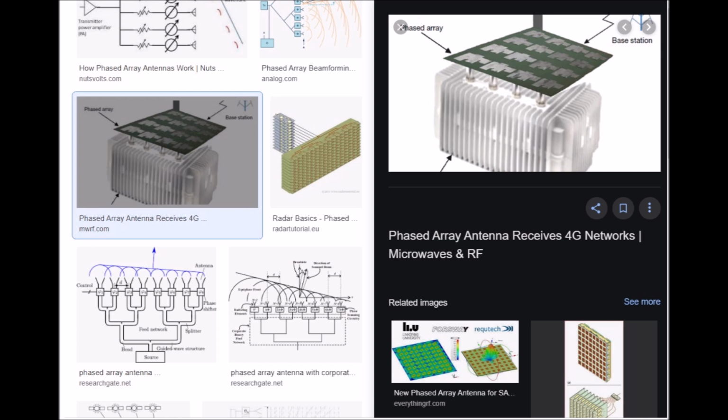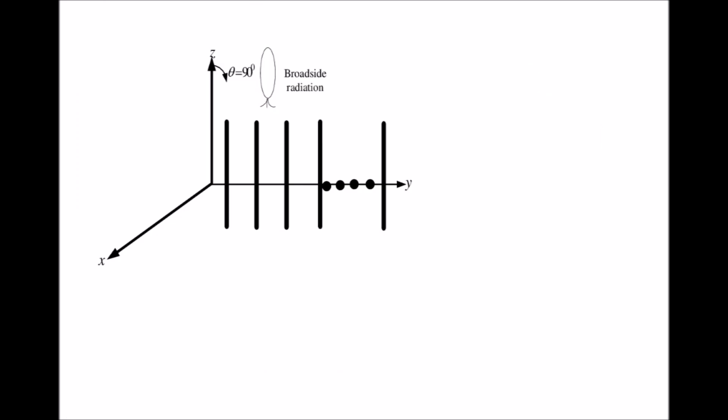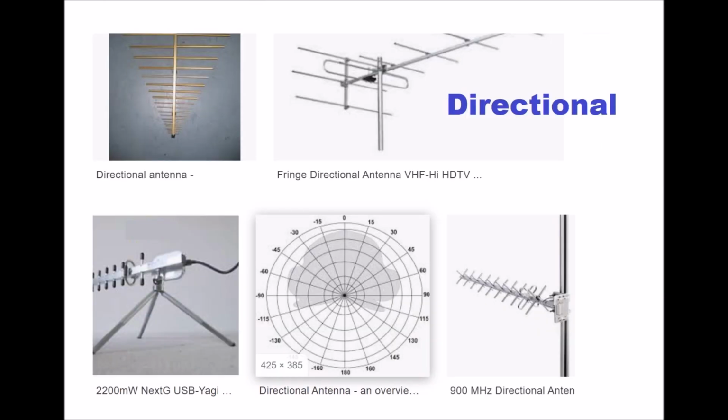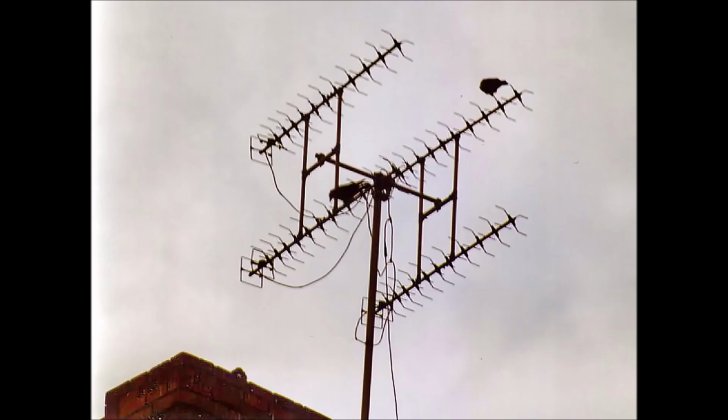The same combination of dipole antennas can operate as a broadside array, directional normal to a line connecting the elements, or as an end-fire array, directional along the line connecting the elements. Antenna arrays may employ any basic omnidirectional or weakly directional antenna type, such as dipole, loop, or slot antennas. These elements are often identical.